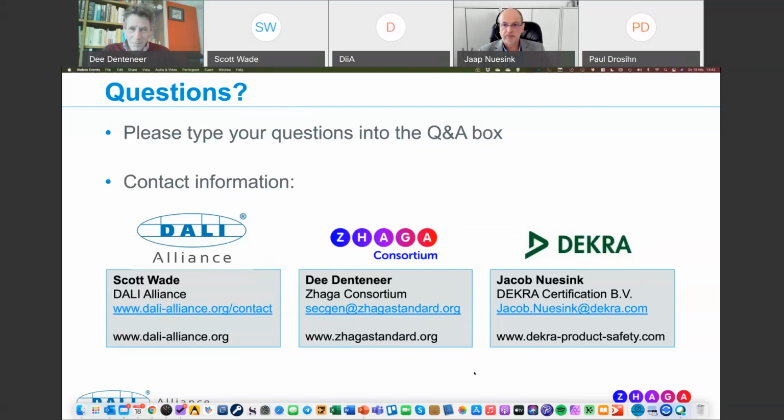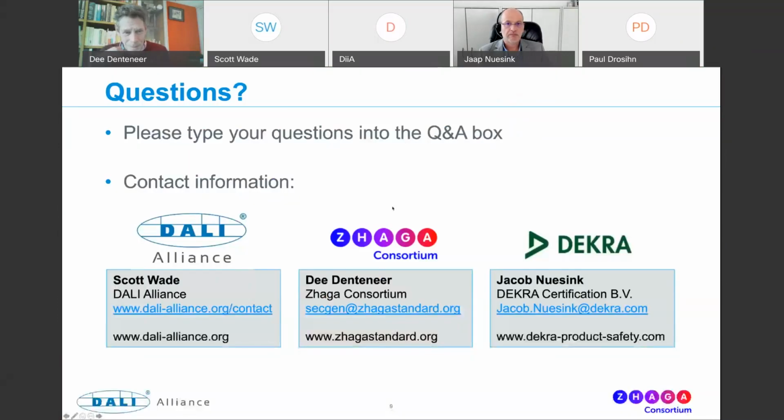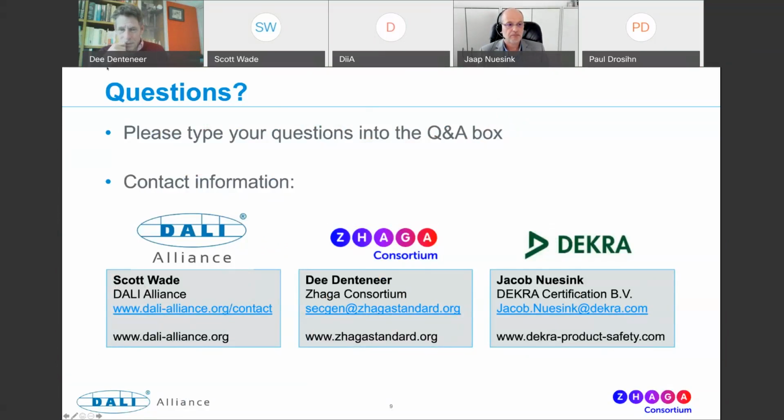Referring to Luminaire data part 251 containing pre-stored Luminaire information, does the specification indicate how to manage this information when multiple control gear are inside the same Luminaire? Is this covered in the test specs? So the requirements for Luminaires, yes. The control gear itself is supplied to the Luminaire manufacturer with the memory bank empty. In our D4i requirements, there's a minimum set of information that needs to be in there. The GTIN is the minimum, which is pretty simple, but it is recommended to put more information into memory bank one about the Luminaire and the lamp.